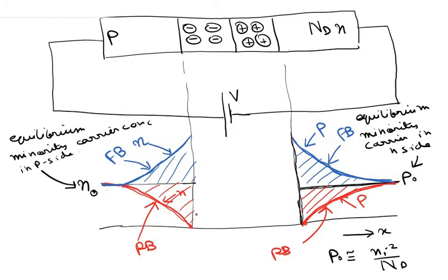Okay, so this again is analogous to the behavior of a capacitor, just as I stated that in a capacitor, with change in voltage the total charge also changes. So here also, as the diode gradually moves from forward bias to zero bias condition, as the voltage gradually decreases across the diode, this excess minority carrier concentration, or the accumulated minority carriers just outside the junction, must actually be removed. So this is equivalent to charge removal actually.